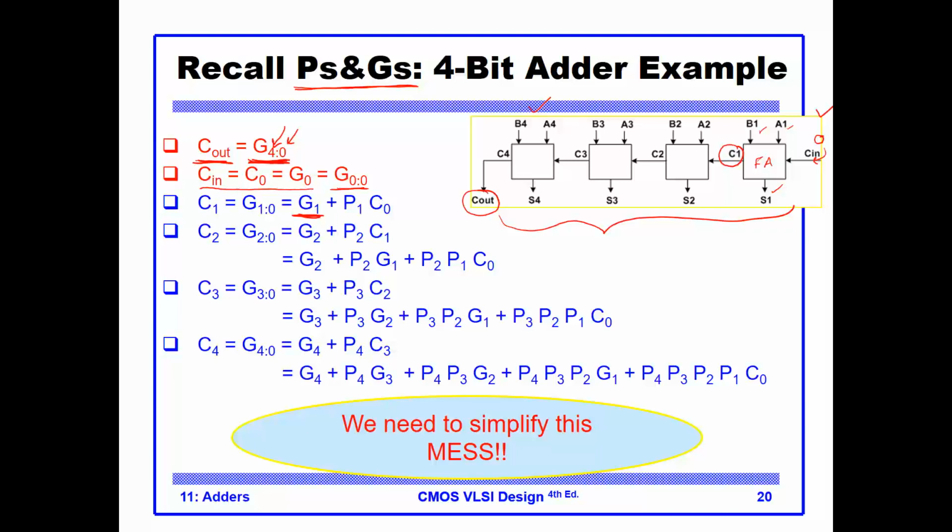Or, suppose this is not the case, the other case is that I have a 1 coming at the Cn, and then I'm able to propagate it. And what would the condition be? This is when Cn equals 1 and one of the A or the B is 1. So P1 means here A1 exclusive or B1. In that condition, I can take the Cn, or C0, it's the same thing,